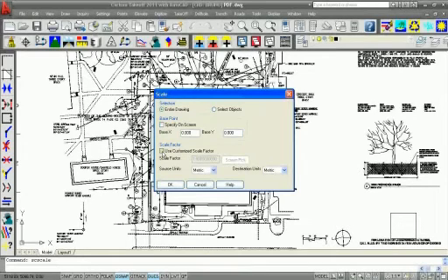But if I uncheck this, you can see some other scaling options that are going to be useful with other drawings. If you're bringing in a CAD file and say it was in inches, it was an architectural, and everything you do, you want to be working in US feet, you can see the scale factor is grayed out, but it's 0.083333, repeating. So the program automatically knows those conversions and will scale the drawing accordingly. It's not something that you have to type into your calculator each time to figure out how to take a US feet drawing into metric. It will calculate that scale factor for you.